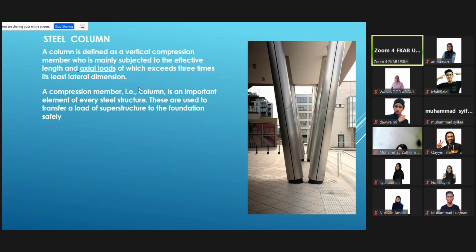So you see some of the British colonial buildings, government houses, government buildings, most of the design is based on columnless walls, columnless buildings. They are using load-bearing walls. So the brick wall is a beam that transfers the load to the ground. It has a strip footing, which transfers the load to the ground.